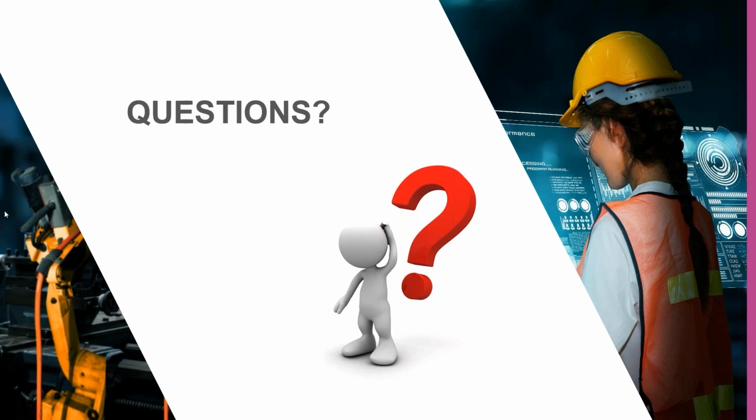James, you asked, can you shell that, add ribs, etc.? So you're talking about once you're done with the Freestyle model, yes, you can. Not only can you shell it, you can apply a solidify. In fact, you have to do one of those to even start to use some of the other modeling features, such as rounds and ribs and things like that. So that is what's nice about when you're done with the Freestyle model itself, you can bring it back into the regular modeling space once it's solid, and then go from there.